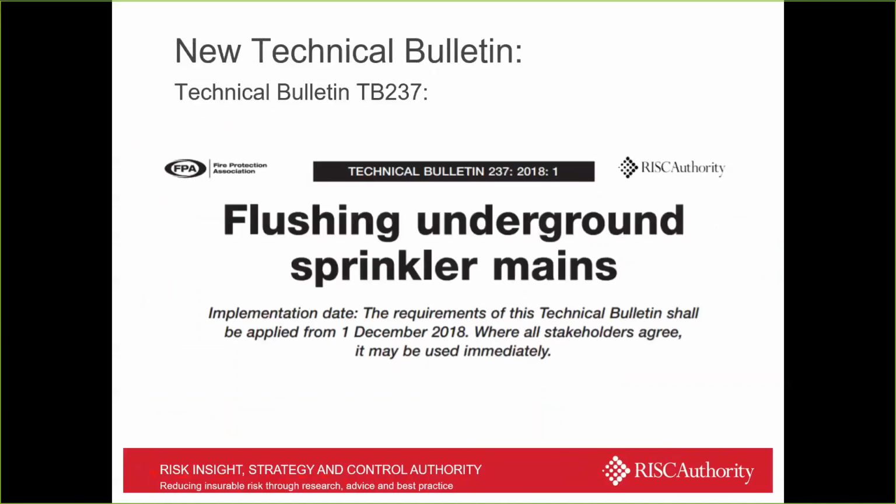Then we move on to the flushing document, which is the new technical guidance document now on flushing underground mains. Obviously, if underground mains are installed in non-clean laboratory situations, in the bottom of trenches, it's quite possible to get debris and contamination into the pipe. And when we say underground sprinkler mains, that can be any main related to the sprinkler system. So it could be the tank infill main, it could be the pump delivery main between the pump house and the building. So any underground mains are captured by this TB.